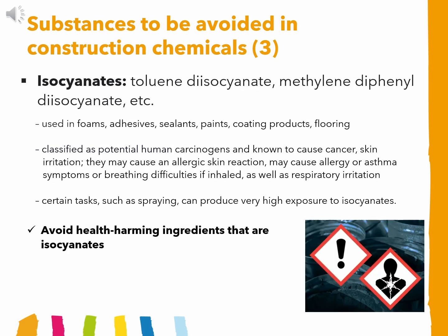Another group of concern is isocyanates, used in foams, adhesives, coatings, and flooring products. Isocyanates can cause skin irritation, allergic reactions, asthma, and serious respiratory problems. Exposure can be especially high during spraying applications. Whenever possible, avoid products containing isocyanates and choose safer alternatives.